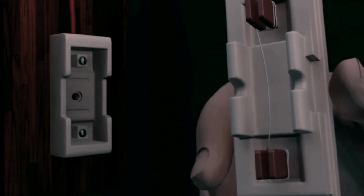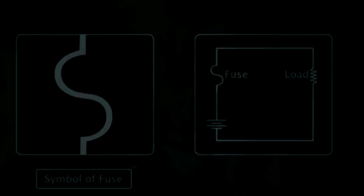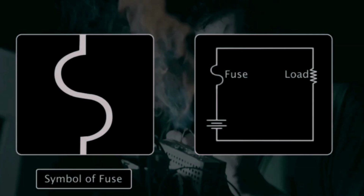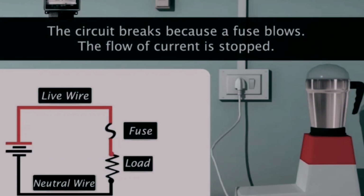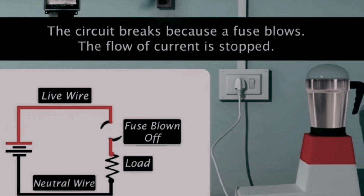A fuse is a safety device. It is a short wire made of an alloy of lead and tin. The alloy has a low melting point and low resistance. The thin wire is set in porcelain casing. The fuse is represented by a symbol as shown in the circuit. The current flow should not exceed the safe limit. Since the fuse wire is thin, has a low melting point and develops high resistance, it prevents the flow of excessive current in the circuit. Thus, we can protect costly equipment from damage due to overload or short circuit.